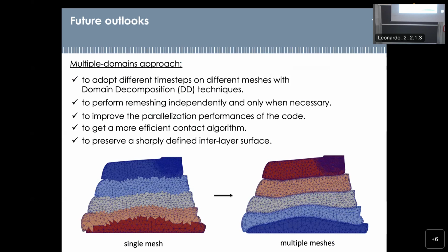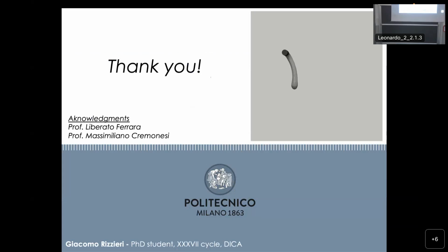And finally, probably the most important thing, we would like to introduce domain decomposition. So the idea is that on different meshes we can use different CFL conditions, so different time steps, integrating time with different time steps, thus increasing the computational power. And with this, I've concluded.